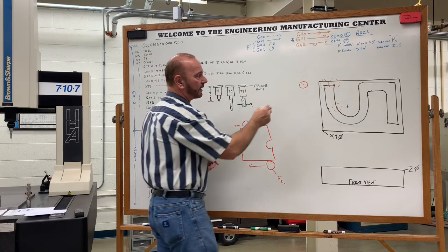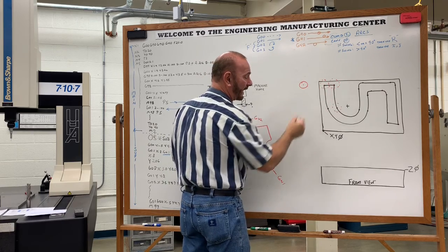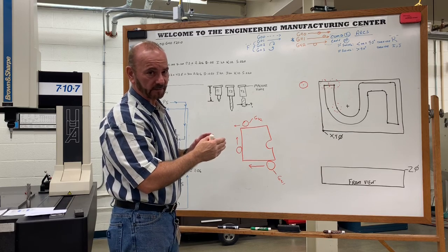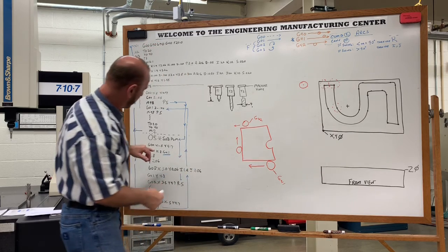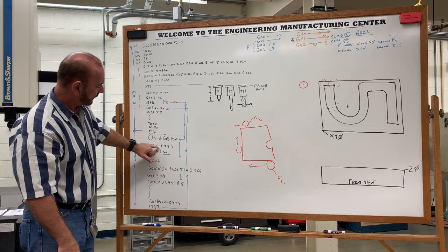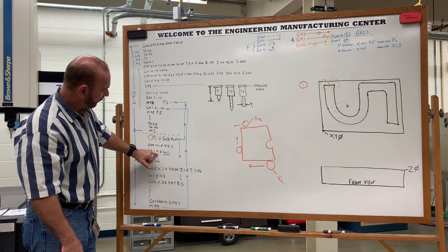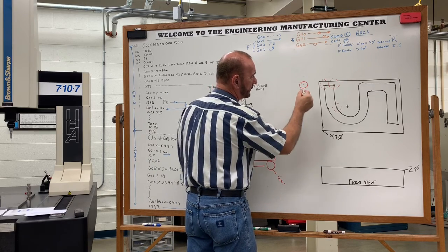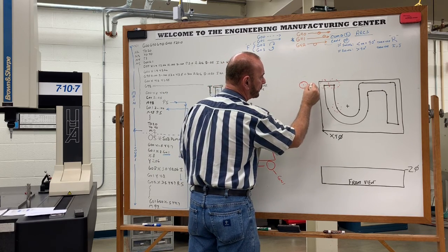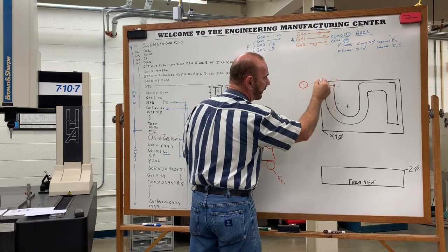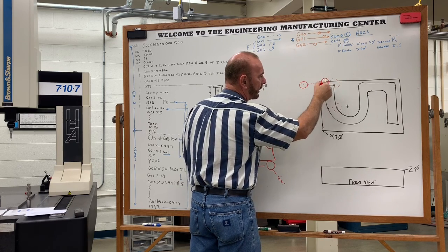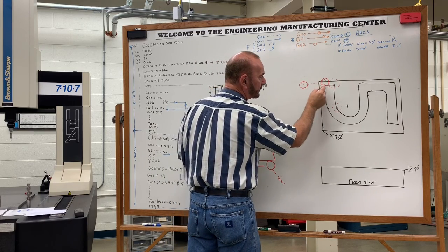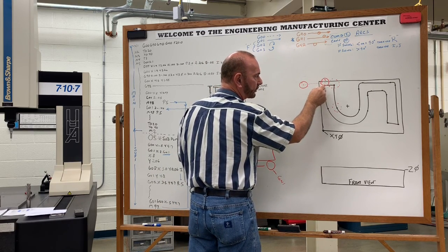The distance that the cutter needs to travel in order to engage cutter compensation properly has to be greater than the tool's own radius. In this case, where the cutter was sitting at X negative 0.5, it now is going to go to X 0.3. And when it goes to X 0.3, it begins this movement of slowly moving to the left of this particular point, and the computer calculates where it needs to go so that when it gets to that point, the cutter is tangent to the point.